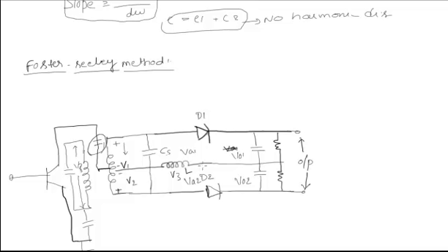So you have V3, which is the input voltage here. We have two different diodes arranged here. Let the voltage across this part be VA1 and the voltage across this part be VA2. After the diodes, let the voltage across this part be V01 and the voltage across this part be V02. The output voltage will be equal to the difference of these two voltages.